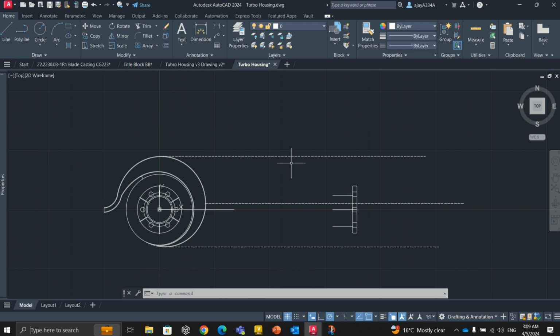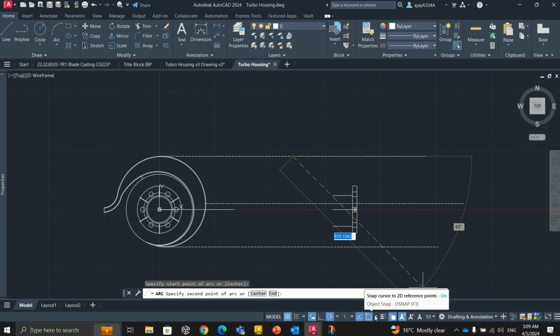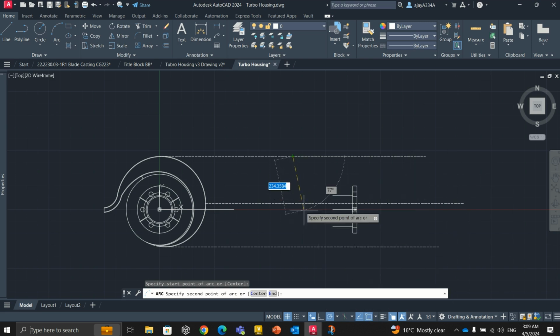You then, in addition, have to understand how the layering of the object works as well. So if you look at an object from the top view, you need to understand what is hidden behind the top view. So then you can start adding your dotted and dashed lines in order for the hidden views to be shown as well. In addition to that, then you also need to envisage in your head what the product looks like from all 3 dimensions, all 3 angles.